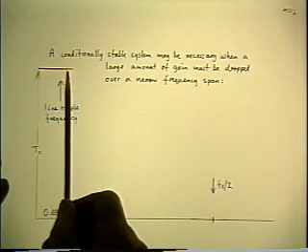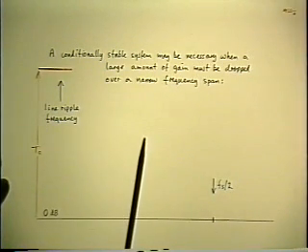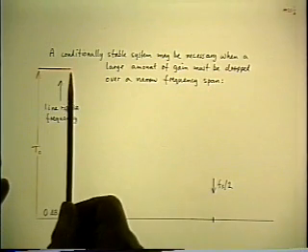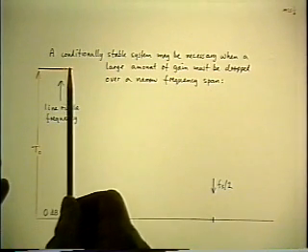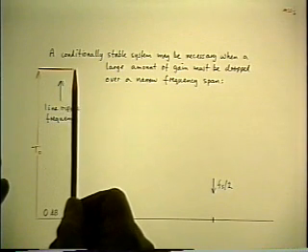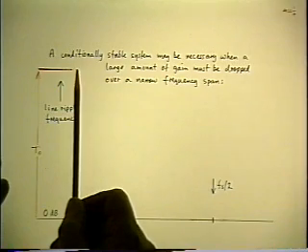But you also have to extend that all the way up to 20 kilohertz to get the benefits. So let me shift the scale on this diagram and say this is now 20 kilohertz. I have to maintain 40 dB of feedback up to 20 kilohertz to get all the benefits of feedback up to that frequency. Okay.